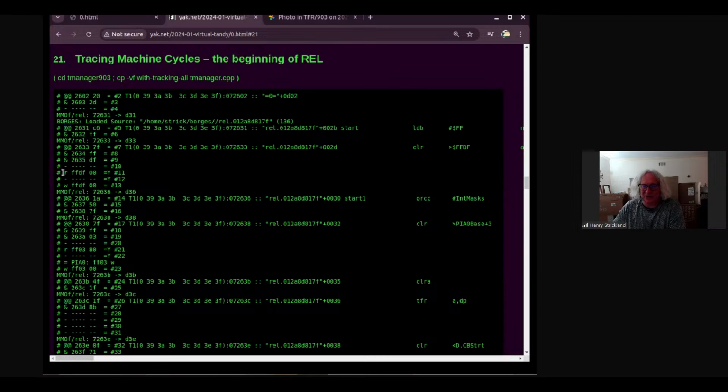And then extra read cycles and extra write cycles that are doing data, like how does one clear FFDF? Well, look, 6809 or 6309 clears by first reading the register and then writing it. And I didn't know that. I don't know that emulators emulate that correctly, but we're running on a real vintage CPU and we're actually logging every cycle it does. And so I can see things like that. I think that's really cool.